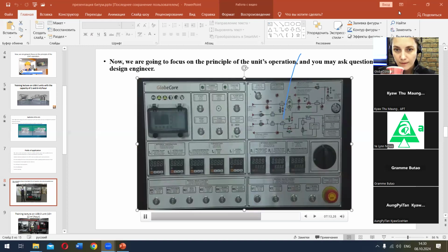On the front panel of the control cabinet, there is a mimic diagram of the unit's operation. Buttons for activation of devices in manual mode, service buttons, and a controller. In addition, the unit features power supply and correct phasing control indications. The control logic is implemented on a Mitsubishi regulator. The power circuits of the devices are equipped with circuit breakers and a soft starter.